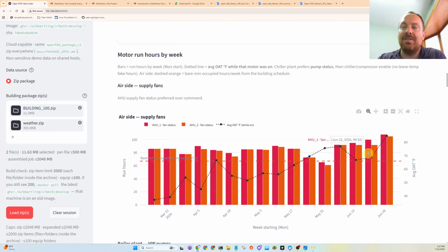Some of the guys will just adjust manually. In really cold weather in winter, they adjust for really long run times, and then in really hot weather, like we have weather extremes right now, they'll override the building 24/7, which is totally fine and acceptable for these weather extreme events, both hot and cold. That keeps the building comfortable, and it's pretty common. It's probably a good thing to do for extreme winter and extreme hot, to just run things 24/7. Hopefully you can back down on the amount of outside air you're conditioning.